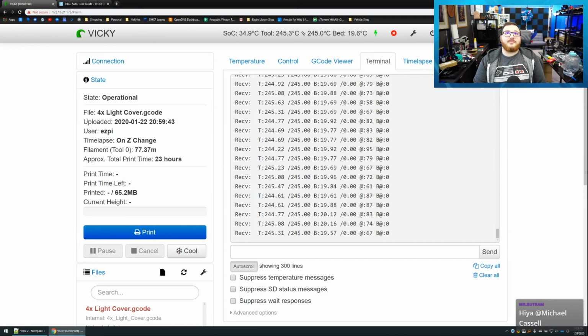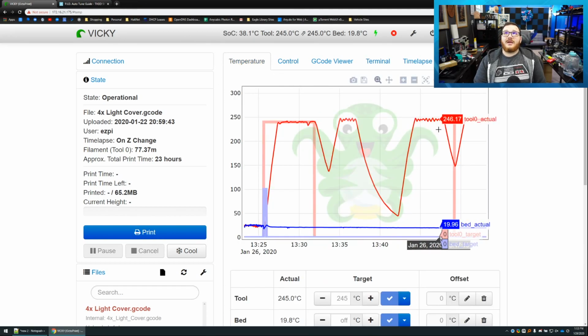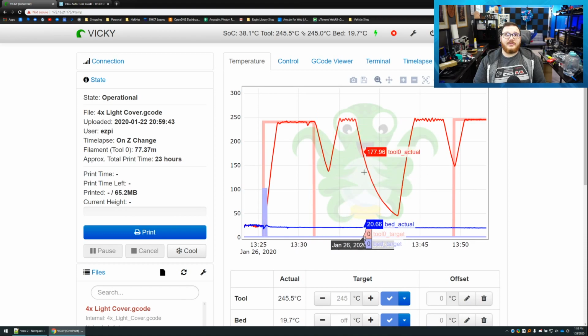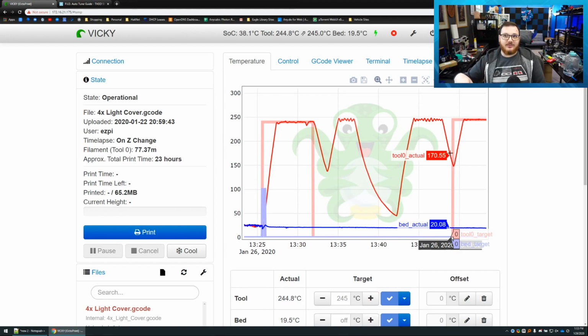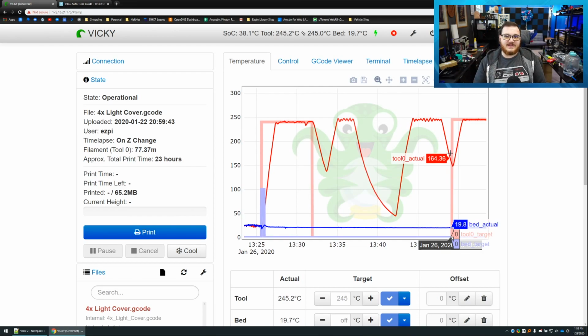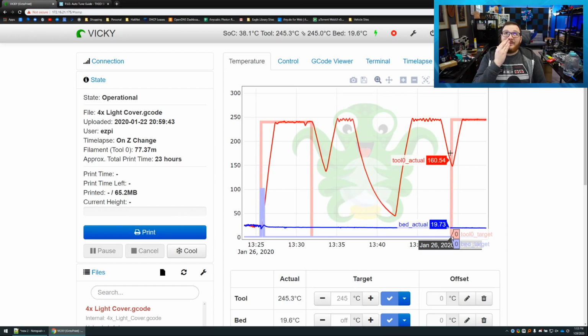So I'll end up putting this machine back into service. I didn't see anything here that indicated that there was any physical problem. What I mean by that is when I fired up the Octoprint instance and looked at the logs, I didn't see that the hotend was shooting up really fast or dropping down really fast. It just looked like it was having trouble getting up to temperature. And I thought, oh, I just updated the firmware. I just reset my EEPROM. It probably needs a PID tune. And then I also noticed that there wasn't a sock on the block.